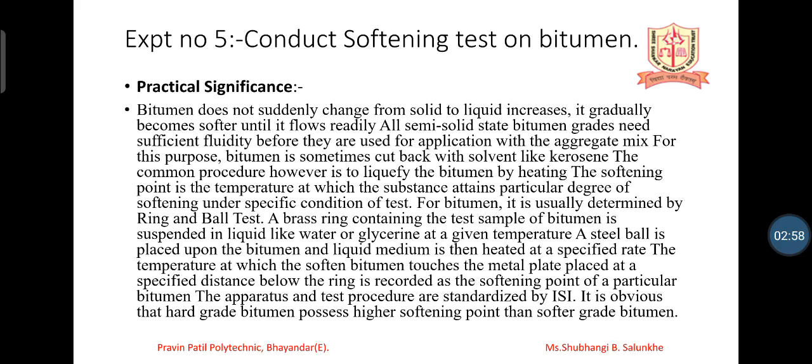Obviously, if the bitumen is a softened grade bitumen and we heat it, it will touch the plate very fast. That is, its softening point is low. Then the bitumen which is hard.